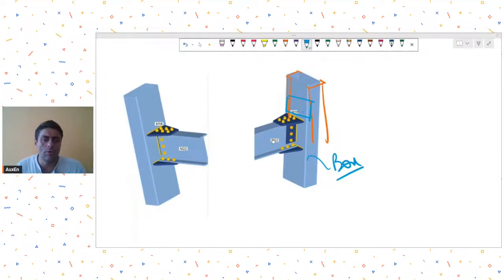If you don't take the same section as you want in your actual design, then the results will not be appropriate. So my request to you will be that if you have taken channels, you should model channels in Idea Statica also. Otherwise, you won't be able to fully rely on the results.